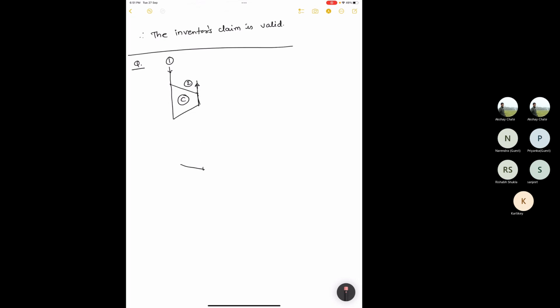Anyway, in this question it is a compressor, and after the compressor there is a heat exchanger, which is called a cooler here. What happens when you compress the fluid, its pressure and temperature both increase, but for the end application you need higher pressure. You don't want higher temperature. So that's why you cool it. The temperature comes down, but the pressure is still high.